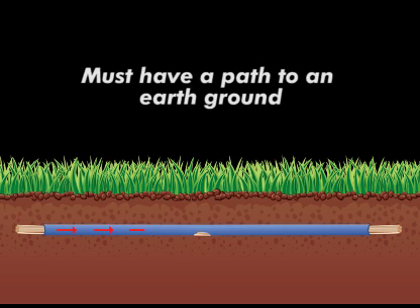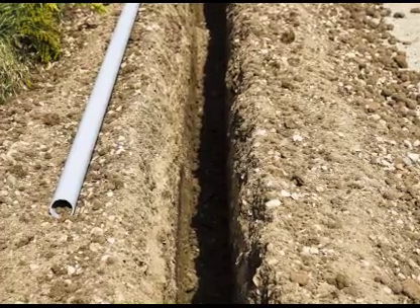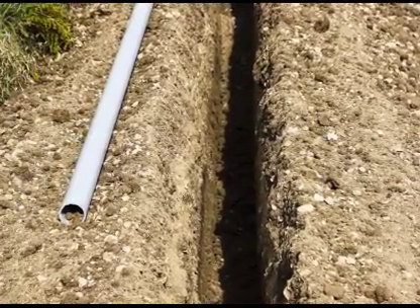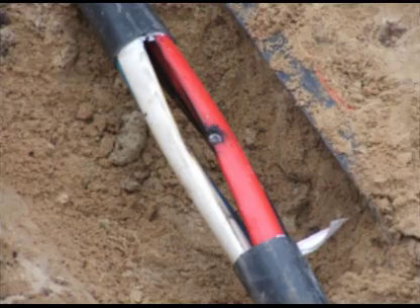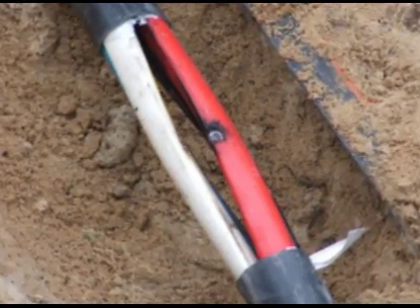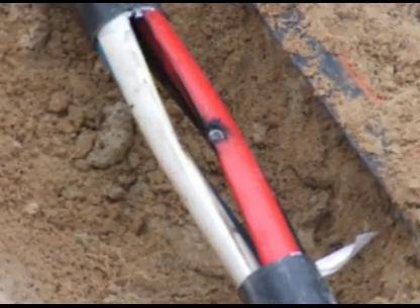A poorly repaired splice with water around it. A current must have a path to an earth ground to be a detectable ground fault. In most cases, a cable contained in a conduit will not have a detectable fault to ground. One exception would be a PVC, non-conductive conduit that is completely severed, exposing the conductors to the earth ground.